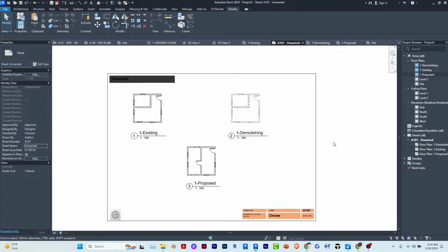I would like you to practice application of materials with regards to what we've learned in Revit, the two methods. I concede that the first method is cumbersome because of the amount of times you have to click even to just get to choosing the materials and the amount of options to edit the materials. There are other softwares that are easier, but it's good to know beforehand what kind of materials you're applying at some places, so that when you go to the other software, all your components don't just become one material and it's difficult to work with. So you will need to break your exteriors into different materials.